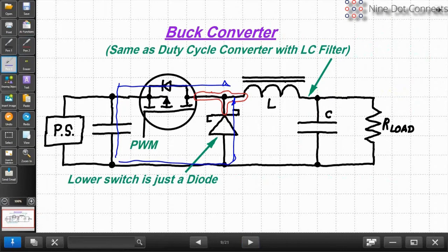So you end up looking at a loop where the current is flowing. Now, if I can keep those two loops on top of each other, if I can keep the top loop and the bottom loop on top of each other, then that would be an ideal way to reduce that type of coupling.